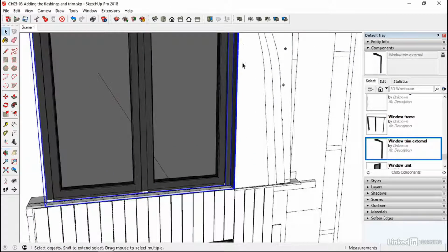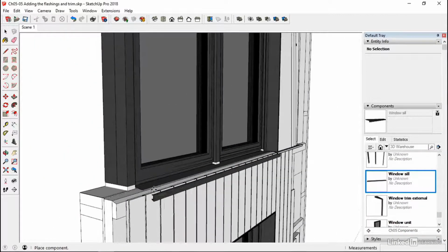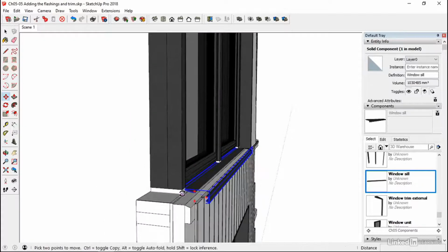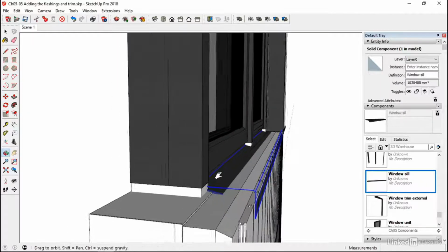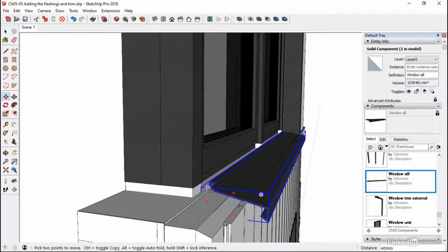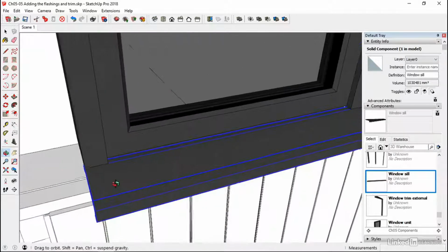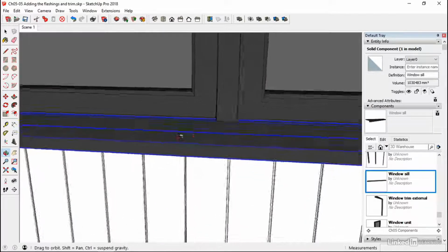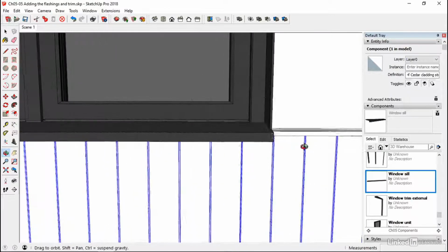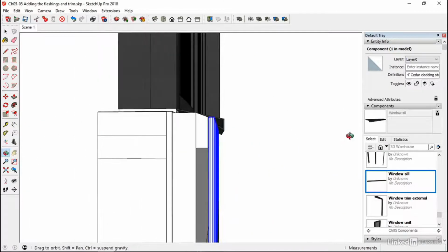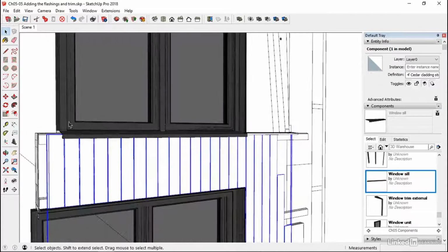So we've got that bit, and then we've just got the window sill, and we'll pick that up, and that goes over this bit. Again, let's just drop it into place and kind of line it through. Trickier than it looks, this. So we've got that little cutout for this, so let's grab it at that point, just drop it in at that intersection there, making sure we've pretty much sealed all around, and that will probably do us for the window. Just make sure that that sits out far enough. Yes, it does. So we've got, again, our oversail drip. So everything looking pretty good.